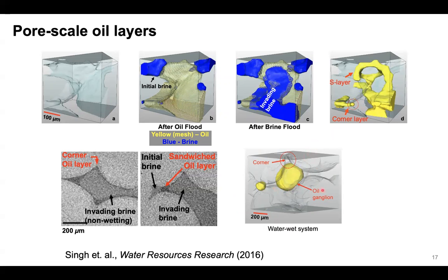So the difference again, residual saturation can be achieved in this system within one pore volume. And here, if we keep injecting water, these layers slowly drain and can produce more oil. But the other thing is that you need quite a lot of water to displace or drain these layers, which might not be economical for industry. We saw this sort of layers also in three-phase flow when we injected gas along with that. But today's presentation is only focused on two-phase flow here.